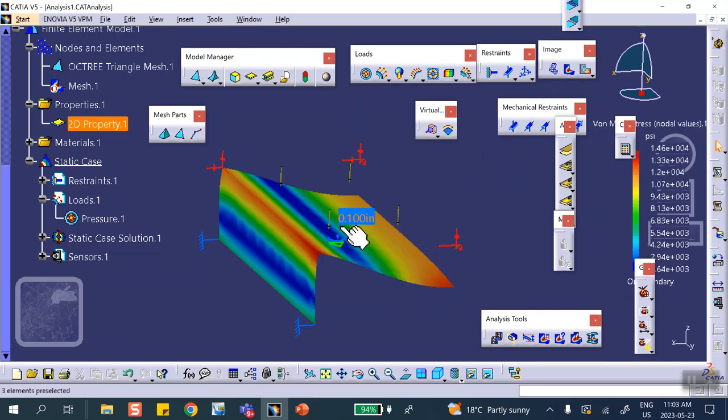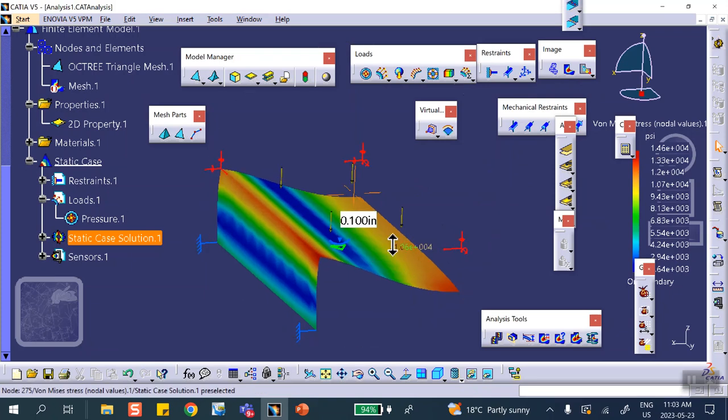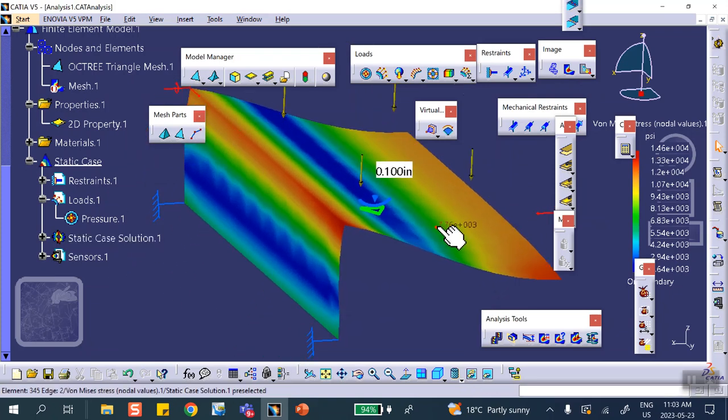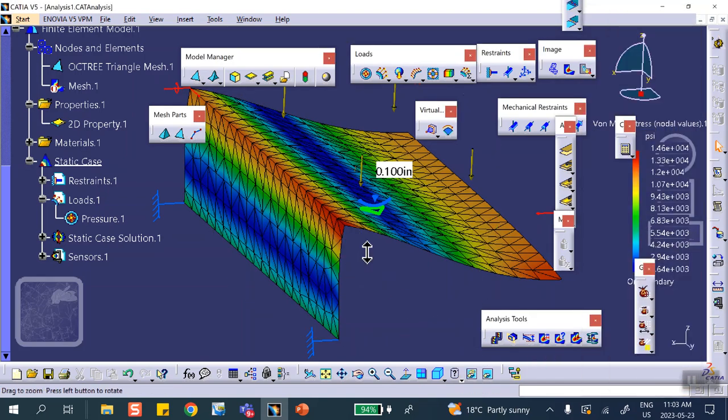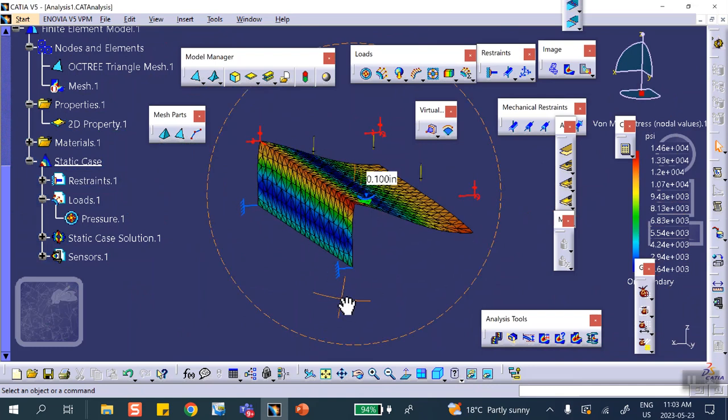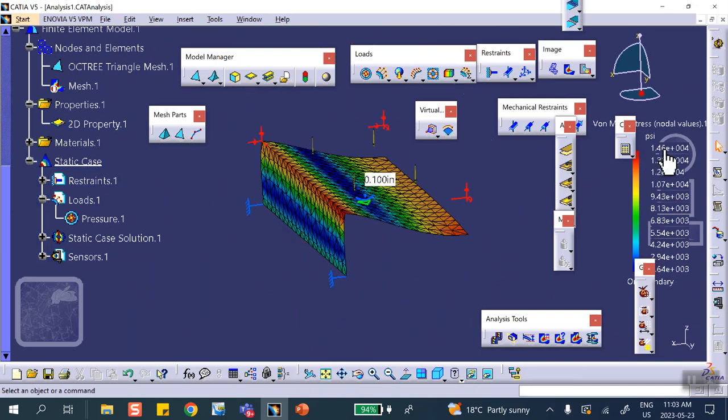Okay? Now, you want to see the von Mises stress? You click on it, and you can see that the biggest stresses depend on the places where the biggest displacements are, and this is where the cantilever position is. It's just like a cantilever beam, the biggest stress is at the wall. Okay, this essentially is a wall for that. And same story, if you want to see the elements, you just click on this rendering, and then you go to the last one, and the mesh elements or boundaries will show. Okay, good.